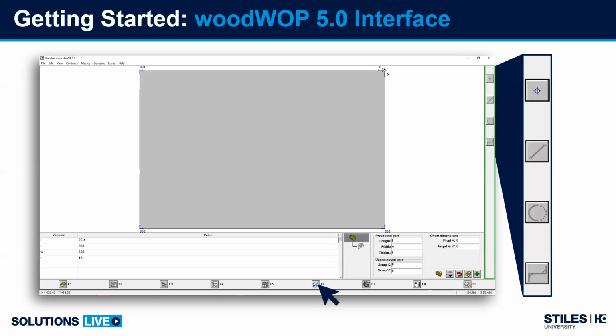When you draw contours in 5.0, F7 allows us access to the tools: the vertical drills, the horizontal drills, the grooving saws, the router motor, router tools. But we have to click F6 in order to access the contour macros.